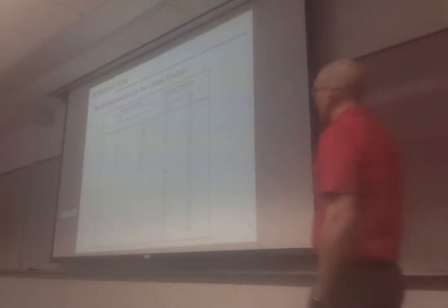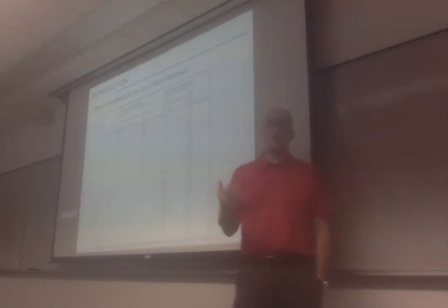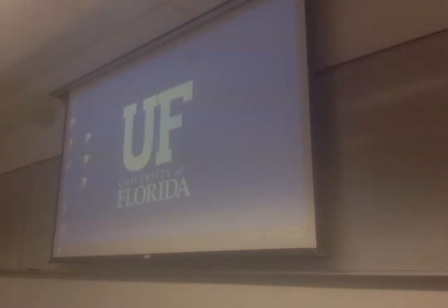So once you know the input frequency and you know the natural frequency of your component, you can go in that table and find the amplification factor and multiply whatever input acceleration associated with the shock to the product is measured by the amplification factor to get the acceleration that will be felt by the product, the critical component.